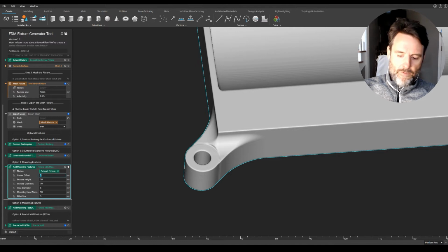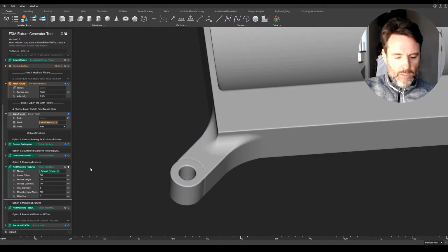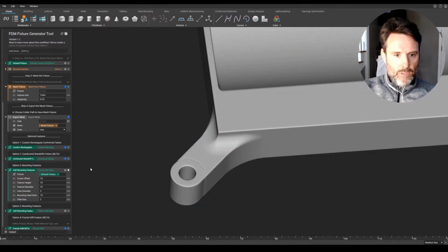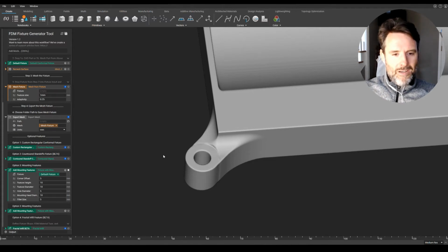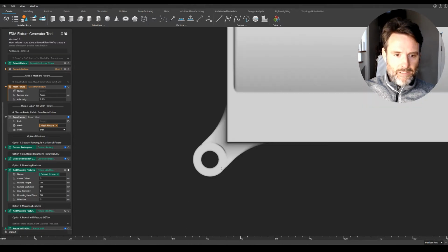Corner offset is the first one. Let me first just go change the value, and I think you'll see pretty quickly what's happening. If I do a series of undo and redo, you can see it's just moving this away in the normal direction. What that number means, though, is that's not how far it's moving in the normal direction. That's your X and Y distance.